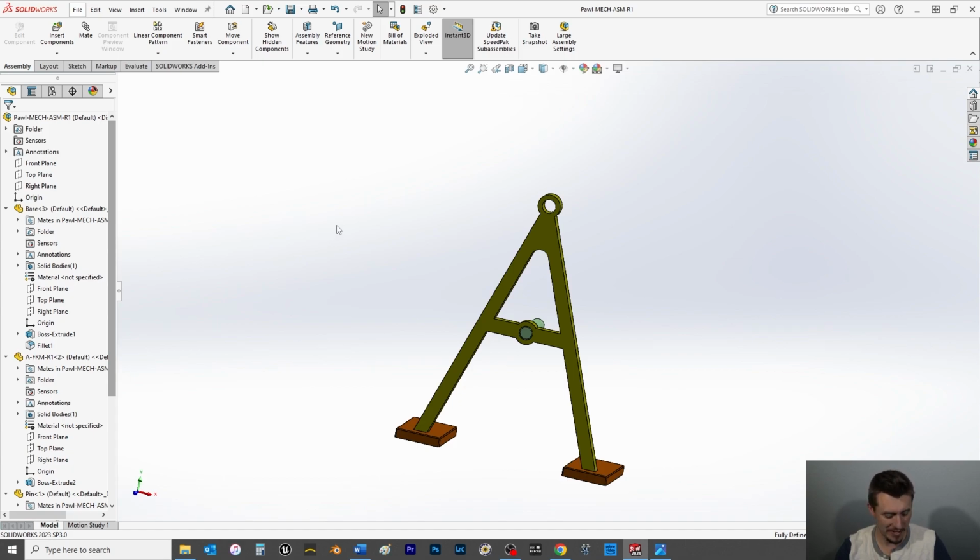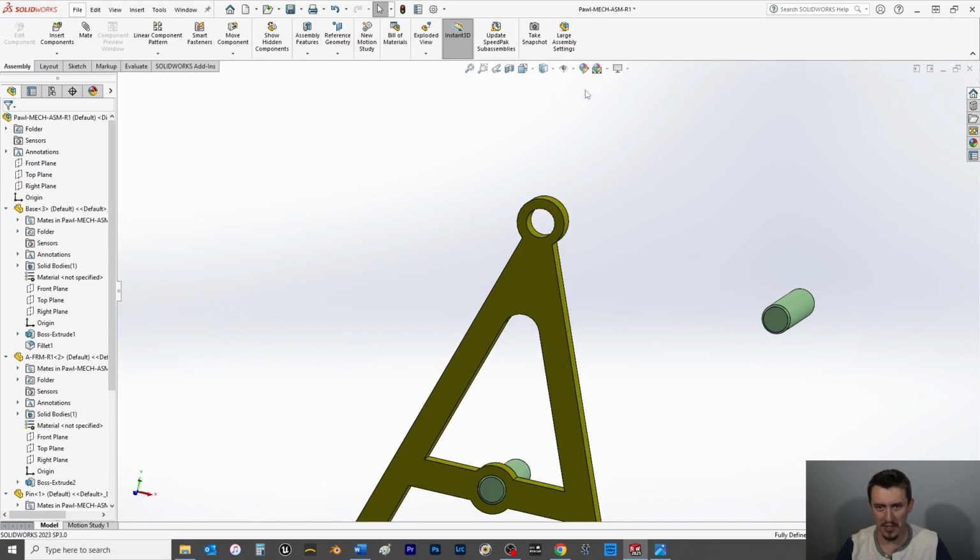And then I can click OK, hit Control S, and now the next thing we'll do here is I'm going to show you this unique trick. You can press and hold the Control key and then click on a part and drag out to duplicate it, if it's in the correct orientation you want, of course. And then I'm going to show you another way to add this in here. We're going to come up here, we're going to go into the visibility icon, and we're going to view temporary axis.